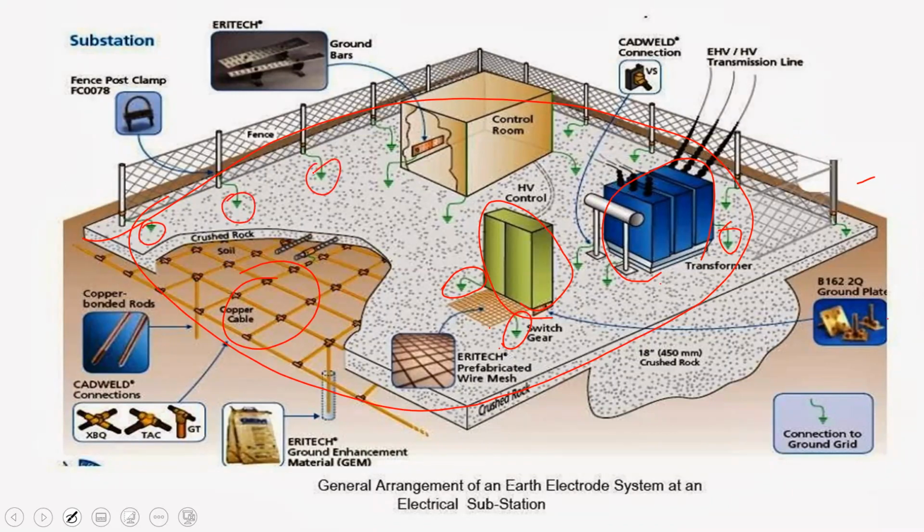Although the company has the sign up front that says high voltage keep out, you're still going to have people hanging on to that fence. If you are holding on to that fence during a fault, you shouldn't really have an issue, because all the fence posts will be connected to the earthing grid. All right. Now, a couple of ways that you can reduce the resistance to the grid.